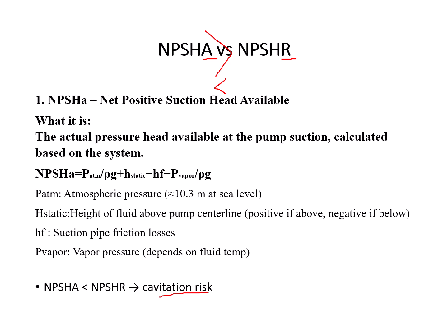We want to select pumps with a lower required suction head. So to improve the net positive suction head available, what should you do? You can lower the pump elevation so as to use a short suction pipe length.